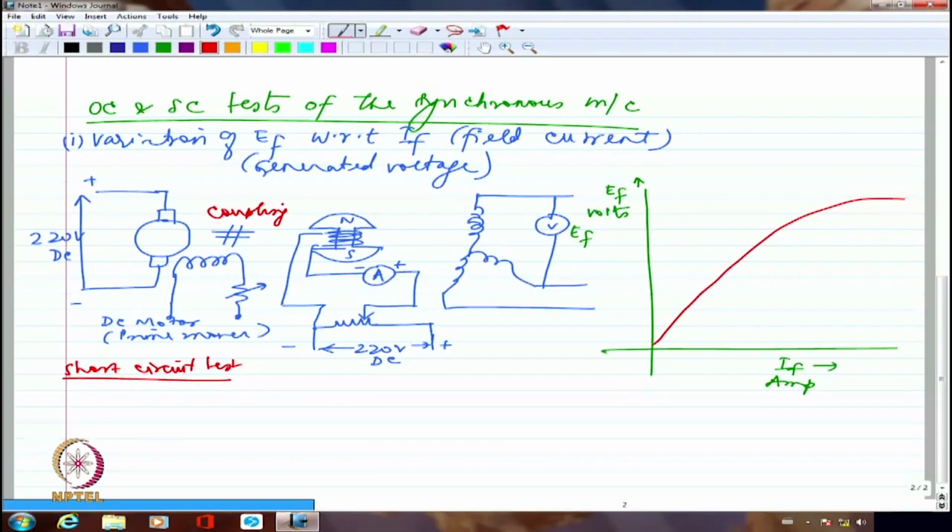So if I provide three-phase supply to the synchronous machine, it will work very beautifully as a motor. There is no problem. In that case, DC machine will work as a generator. And then I can connect a load. That's not a problem. Rather than connecting a DC supply, 220 volts DC, I can remove that and connect a load, resistance load. Rotor will have to get definitely a DC supply no matter what, whether it is functioning as a motor or generator. The field has to be excited.